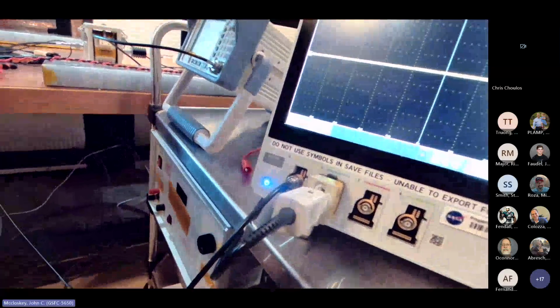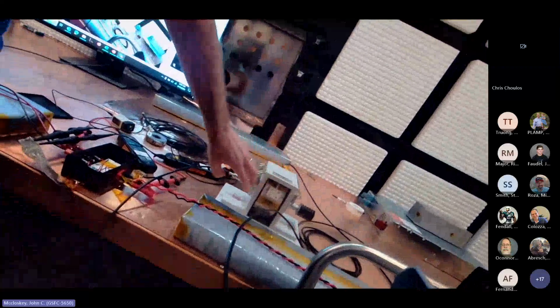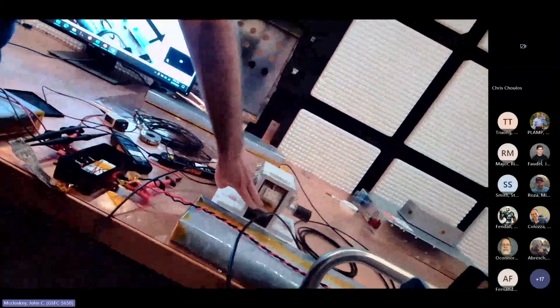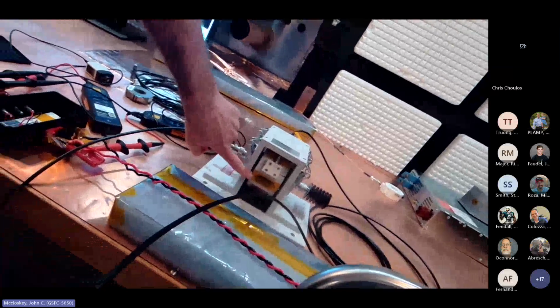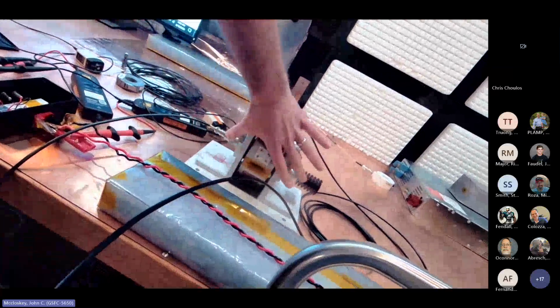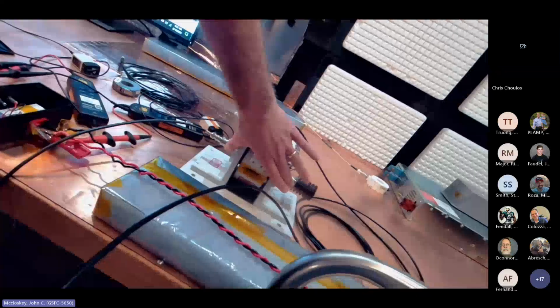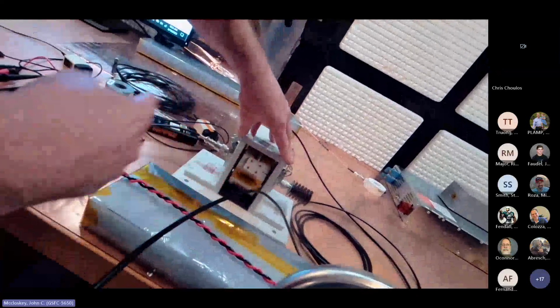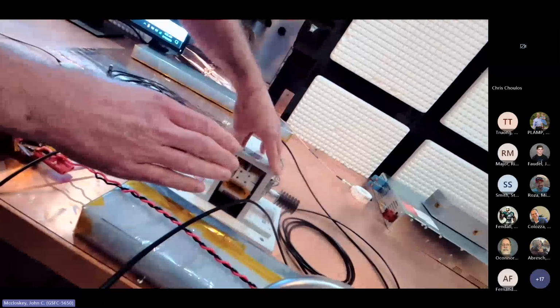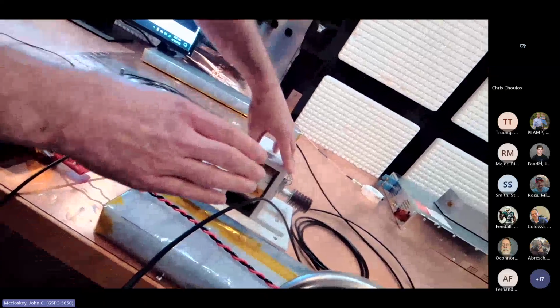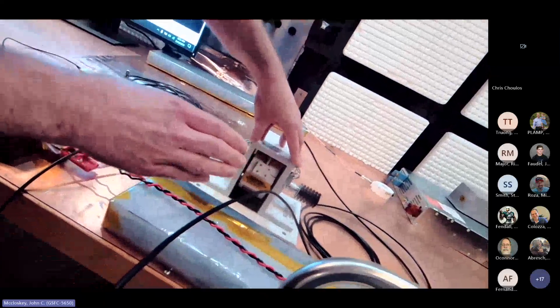But the real key point is that your load, if you look at the induced potential in your loop here, is not 50 ohms, but two 50 ohm loads in series, right? It's a loop current. You might be tempted to think that the 50 ohm resistors are in parallel, and maybe at higher frequencies they are acting more like that.